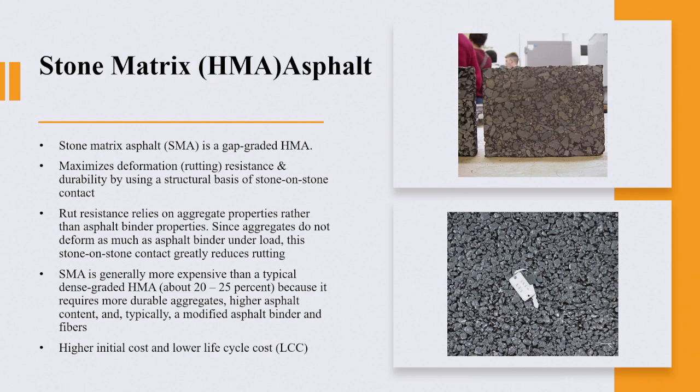So stone matrix is a gap graded mix. You know, in the Gulf states like Dubai, Abu Dhabi, in Saudi Arabia, when I mention the word stone matrix, everybody's silent. They call it gap graded. So basically, SMA is very good in rut resistance because of, again, stone on stone contact.